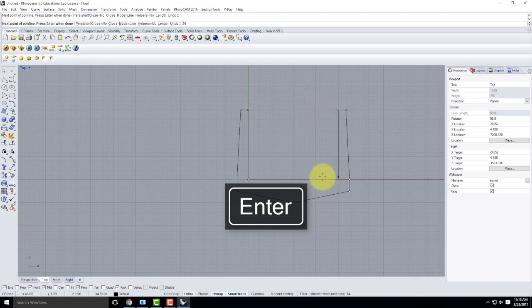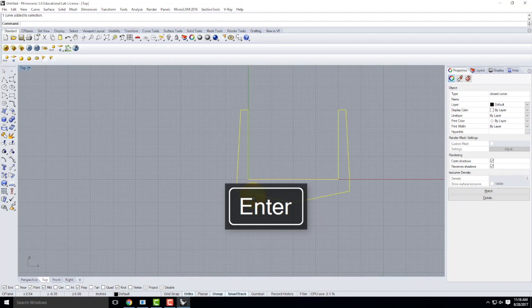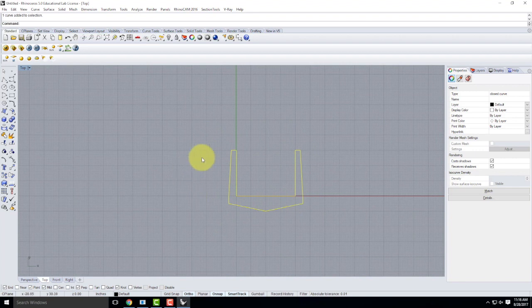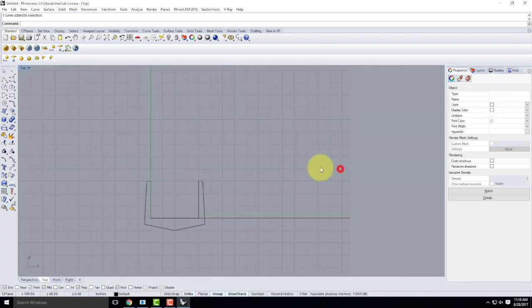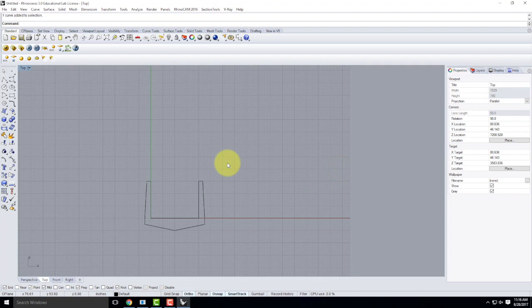Down 36, and I'm going to type C for close, which creates the closed polygon, or polyline, that represents my object, which is essentially what you're seeing on the handout as well. There are, of course, other ways of working through this, and I'll show you as we go along, giving people a chance to catch up a little bit as I go through it.